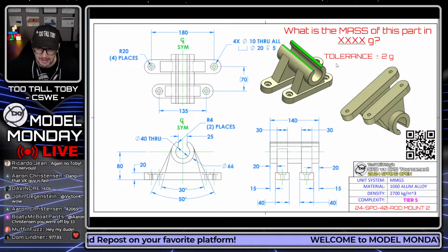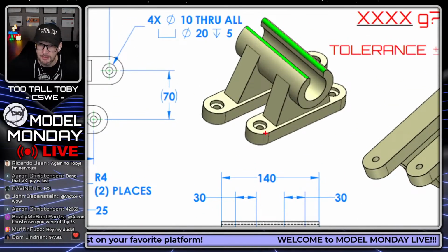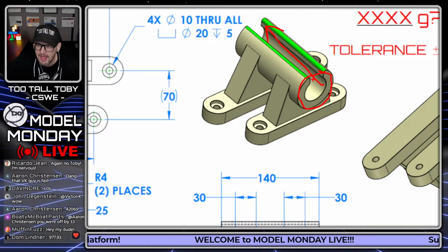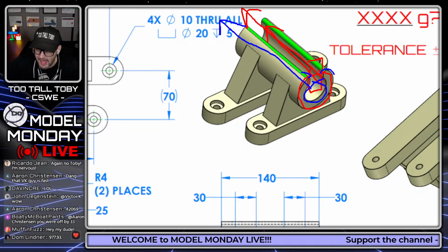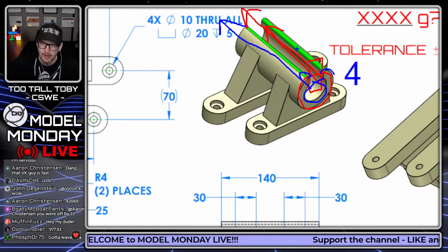3D model like this, I say the same thing: discretize the model. But instead of breaking it up into tetrahedral elements, you want to break it up into individual features. So this first section of the model here, you might create an entire circle and then extrude that as a solid and say that's your first feature. And then you might create a rectangular cut and notch out the middle of this thing, and that might be your second feature. And then you might create that internal circle, and that might be your third feature. And then you might create the fillet here on this edge, and that might be your fourth feature. And so you would end up with 4 separate features there for that region of the model.